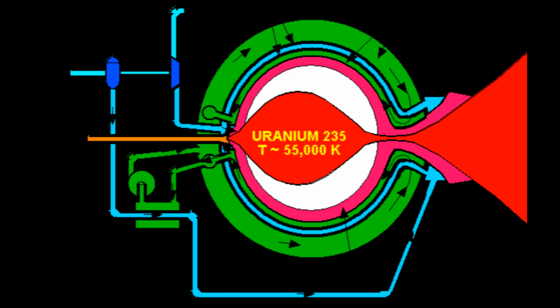If you want to go to higher specific impulse, there is the gas core or liquid core in between, or gas core nuclear thermal rocket engine, which essentially does away with the structure. So you have the little problem that you essentially throw bits of uranium or nuclear fuel into the exhaust stream, and pretty much anywhere you fly this will be nuclearly contaminated afterwards. But for deep space, they are kind of a hypothetical possibility.